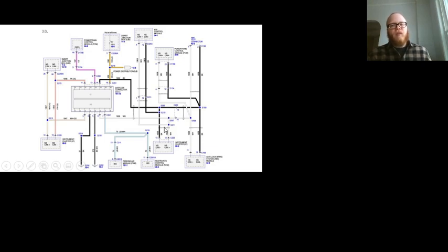And so this shows you how these communication packets are being sent at the same time. Like this is talking and it's spliced to the same wires that this is on, and this is talking and that's spliced to the same wires that this is on and this is talking. So there's just a whole bunch of chatter going back and forth. And the packets themselves make it so that the right information makes it to the right module, and even has the right priority, right? Like if I'm sliding and having a traction control event, that's way more important than knowing what the temperature is outside, right? I agree.